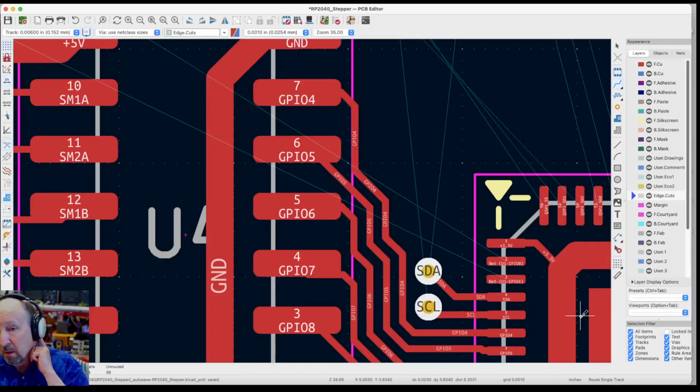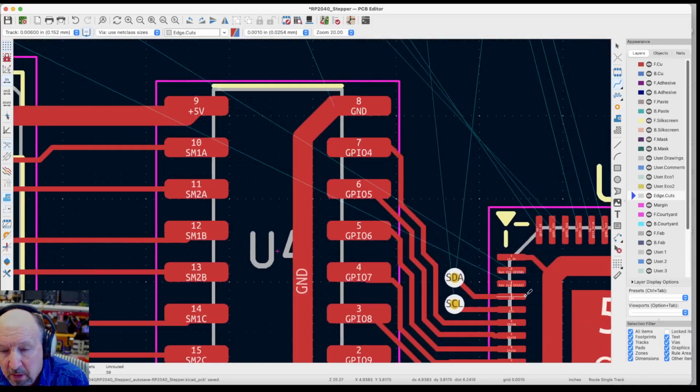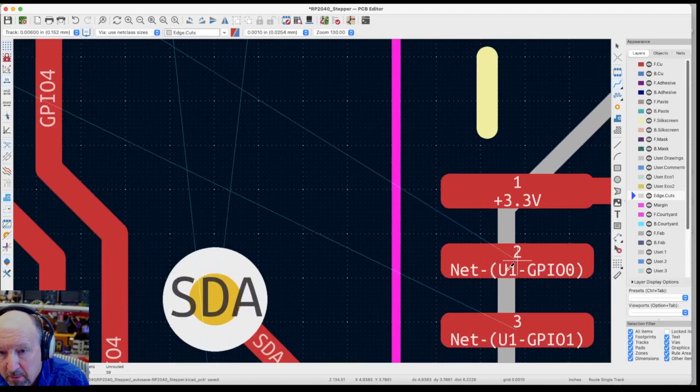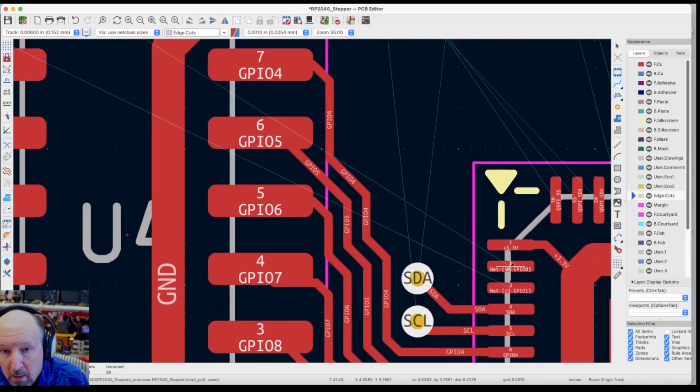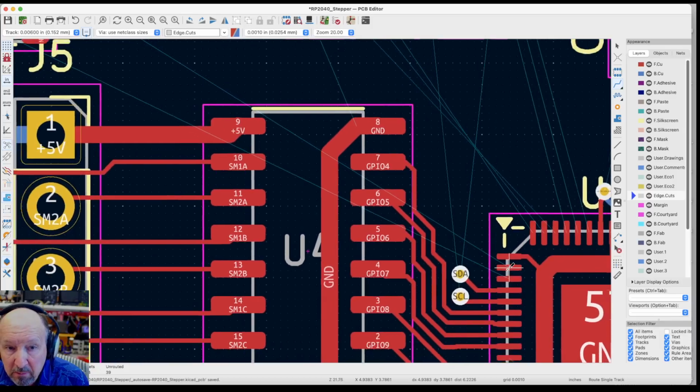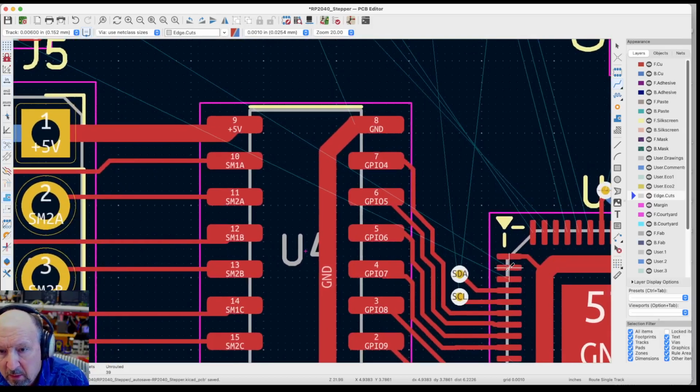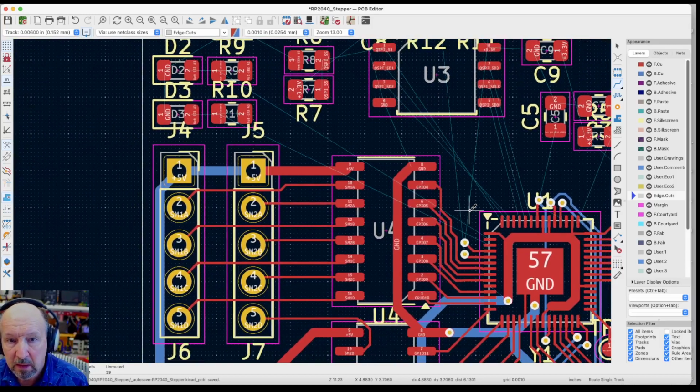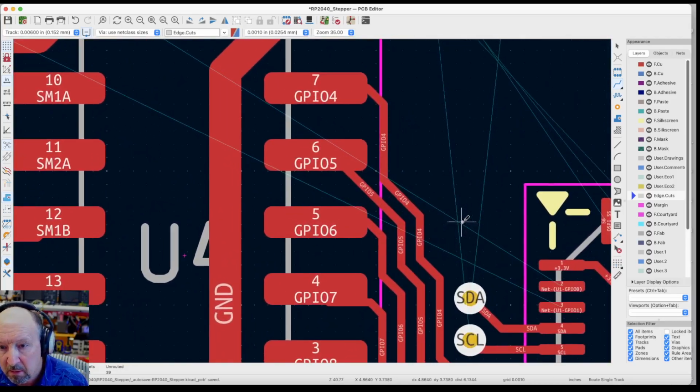Now the other ones are the two LED drivers. Those are the LEDs on these two lines. And so I'm down to the point where any which way I can route them, it'll be fine. Let's put another pair of vias up here for those, and then just bring them through. Or do I have to get anything else up there? Well, the grounds have got to go up. That can be on. Yeah, let's make 2 more vias.